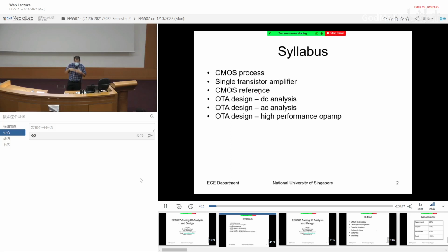So when you build a filter, or any amplifier, usually when you talk about IC design, we eliminate the buffer stage to save power, and we mainly deal with capacitors, so it doesn't draw a lot of current. And this kind of thing, we don't call it operational amplifier. We call it OTA, operational transconductance amplifier. So we'll talk about DC analysis.